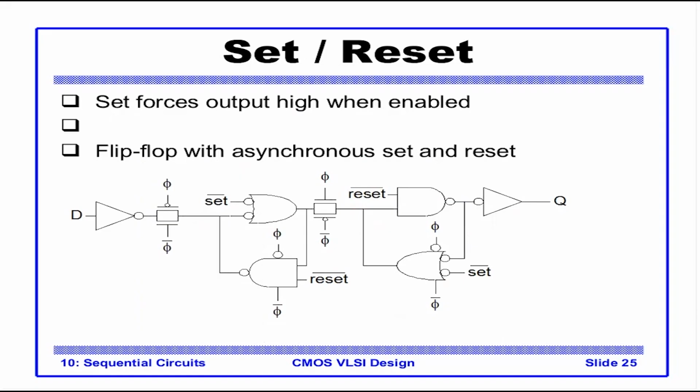There is one more very famous signal called set. Now we want to make sure that Q is 1 instead of 0. It is exactly the same concept as reset, only the gating will change. So this design implements both reset and set in a flip-flop. I would urge all of you to go to Spice, implement this, and see the functionality for yourself.